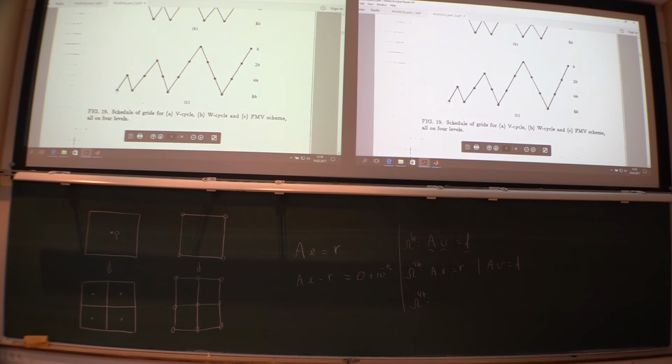You start down there, very easy to find a solution there, and then you try to push this solution up to finer and finer mesh, and you do it like this before you are finally here, first time on the fine mesh level. And then you should have a very good initial start for your unknowns. That can be a very smart way to start the process. And from here on, you will now continue with full V cycles.